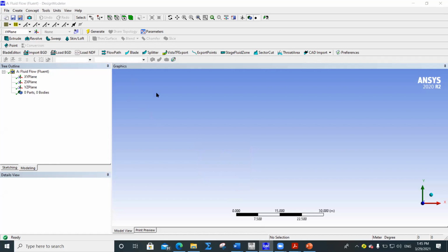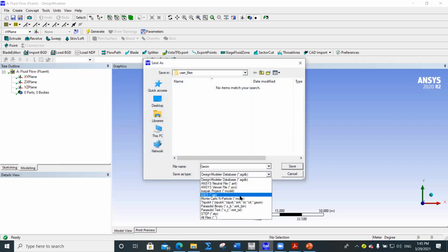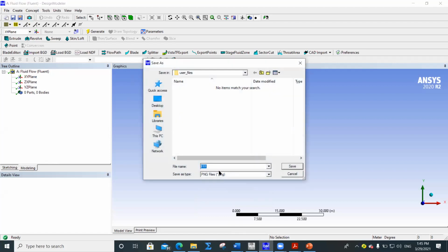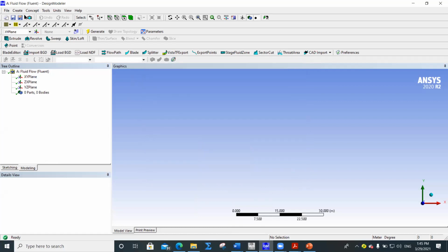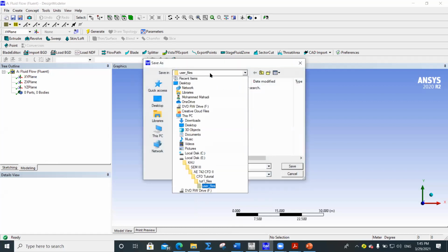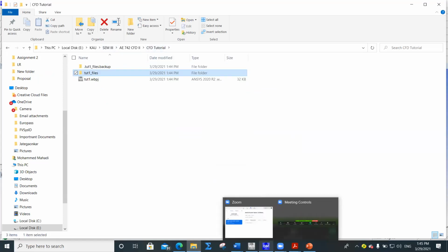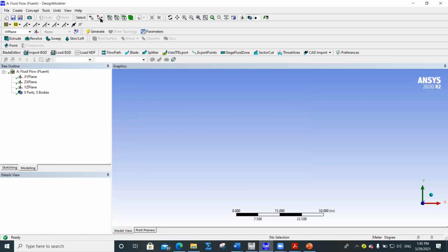This is export. If you want to export your file as IGS or STEP file or any other format. And here you can take a snapshot, and most of the snapshots are saved in user files, all of your snapshots. And then here you can select a point or an edge or a face or a volume. By default, it's better to select an edge here, filter by edge.